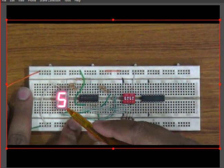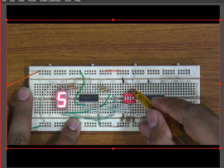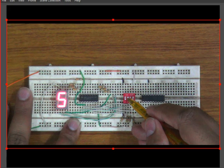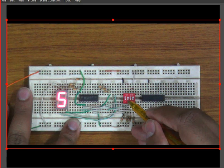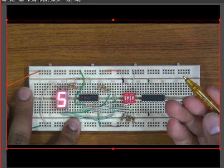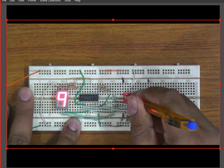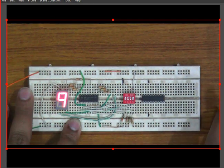Why is 5 displayed over here? Because I have 1 here, as I have connected it with 5 volts. And here, this is 1, this is 2, this is 4, so 4 and 1, I have displayed 5 over there. Now I want to display, supposedly, 9 over there. So what I will do, I will turn this off. You can see now only 1 is displayed, and now 9 is displayed over there.